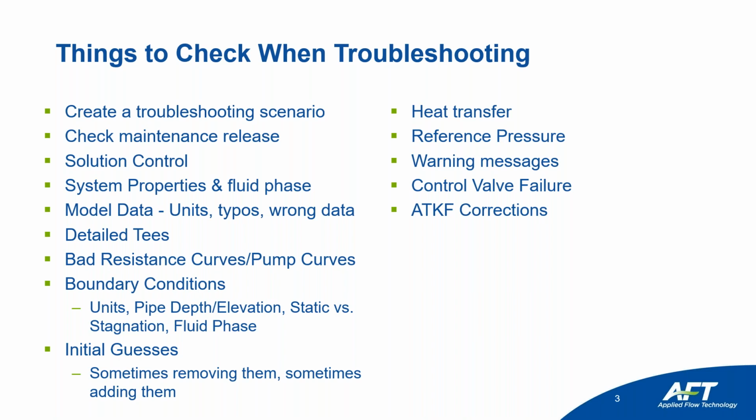And in those types of cases, typically the standard loss models will underpredict the pressure losses when you have those circumstances. So the correction factors will be able to add to that. So when you're running your model, if you see weird results, check your Reynolds numbers, because the software is going to add those correction factors for you by default if you have laminar flow or non-Newtonian fluid properties. That way, it'll give you the actual pressure losses across those types of fittings.